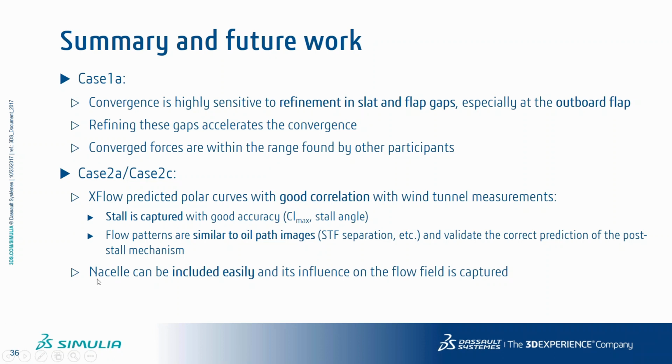And finally, I didn't comment, but for a lot of participants, just including something like a nacelle in your analysis can be a nightmare. It can be weeks and weeks and weeks of work just to introduce such a geometrical element, include it, and mesh the fluid domain, because the geometry becomes much more complex. The gaps between the flap and slat are complex, but introducing the nacelle is also complex and time consuming.